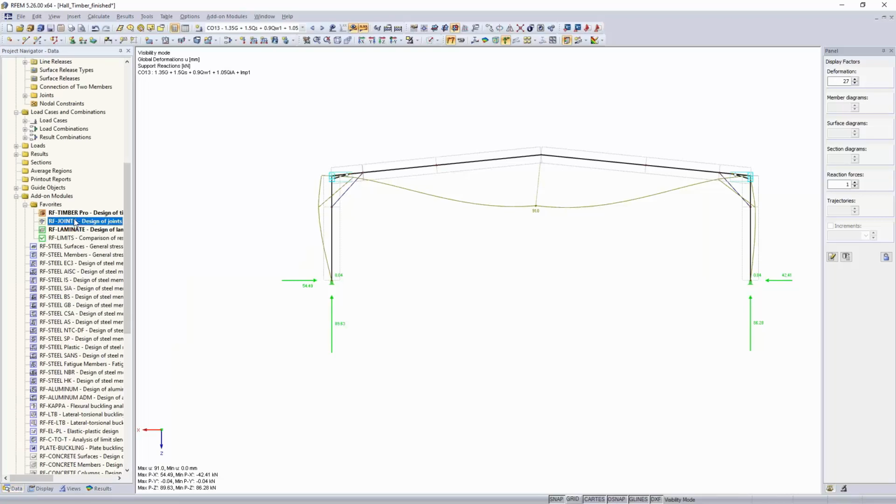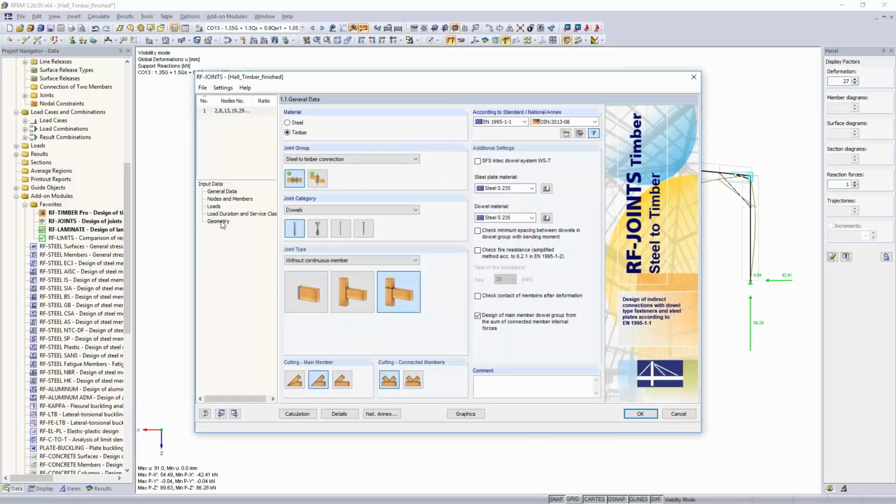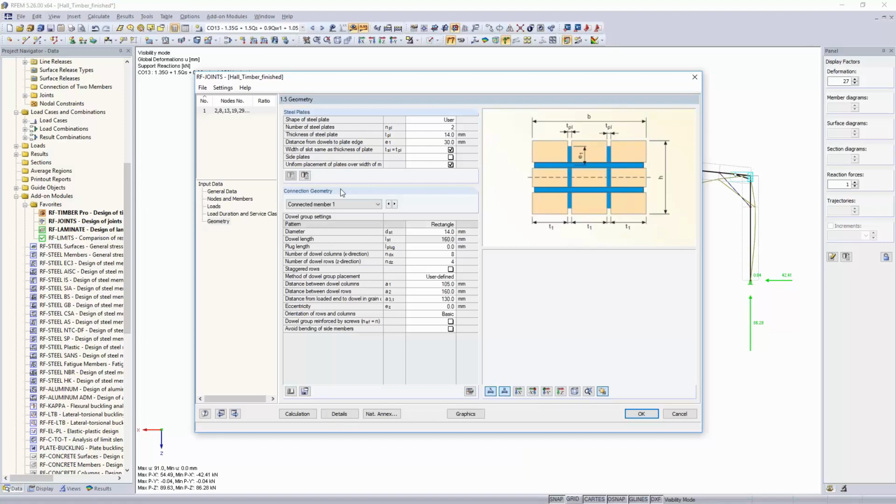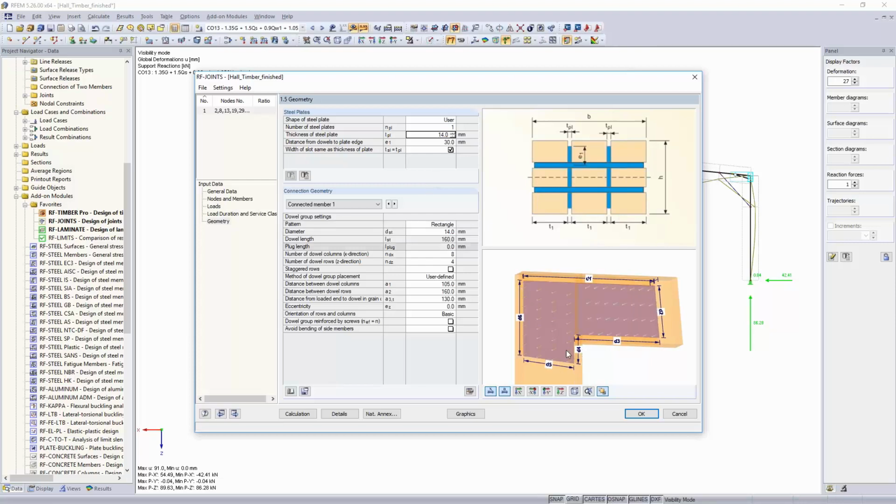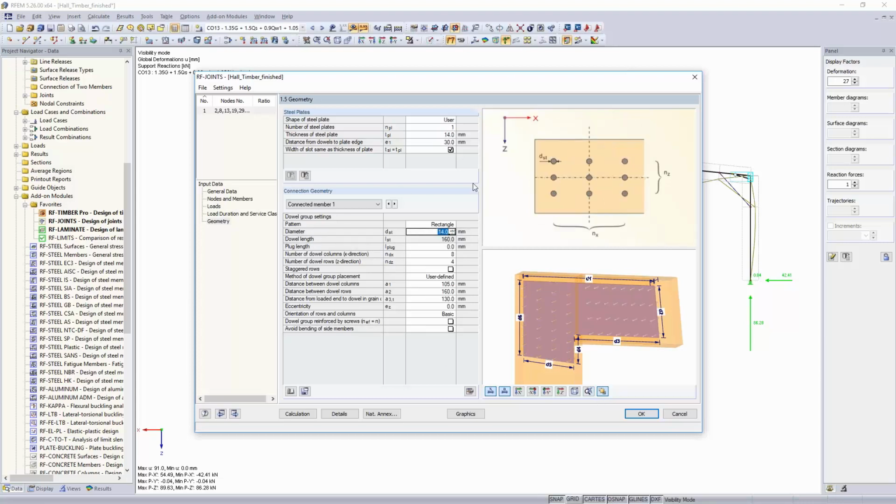So, with this information, we go back to the design tool. We saw that we had a pretty low loading of the steel plate. So to me, even with now a higher loading of the connection, because usually when you calculate with this slip in the connection in here, you have a lower loading of the timber but a higher loading of the connections. That's what you really will find out. But the steel plate was only loaded 7%, so 2 plates probably make no sense in here. And therefore I changed that to 1 plate because I think it's still enough.